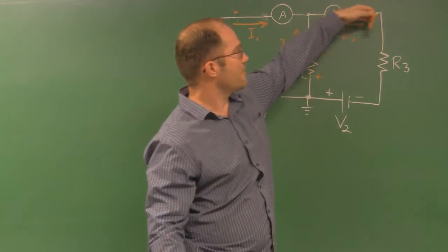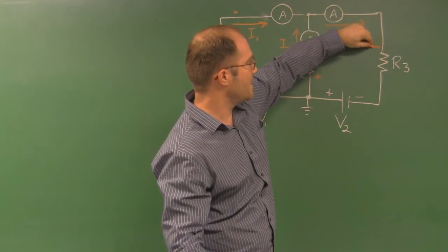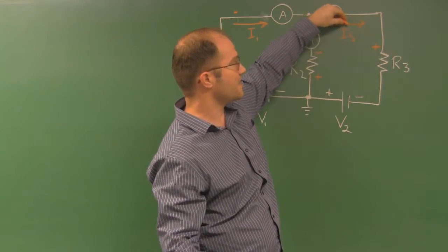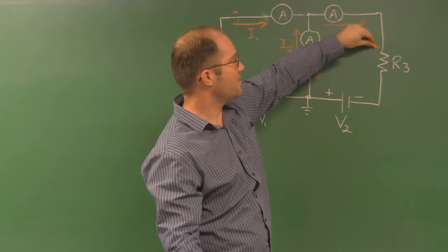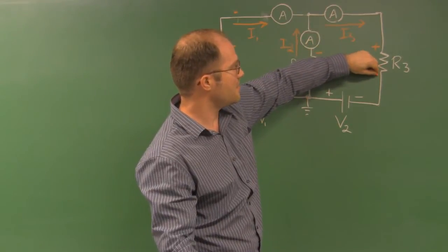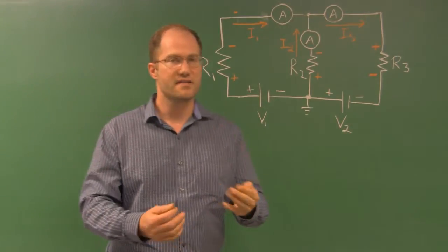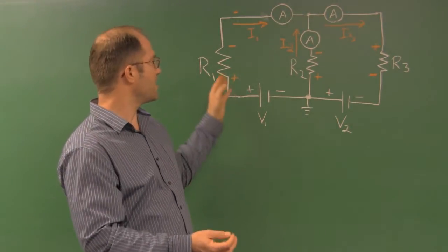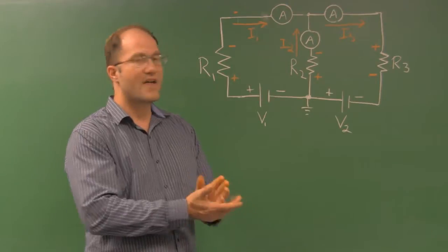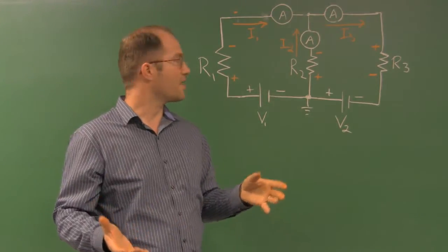And so the arrow will go down through resistor 3. So we'll make the entrance of the current I3 arrow cause that resistor 3 to be positive up here and negative down here. So we've sort of chosen these seemingly arbitrary polarities of our resistors, but that's going to allow us to set up our equations.